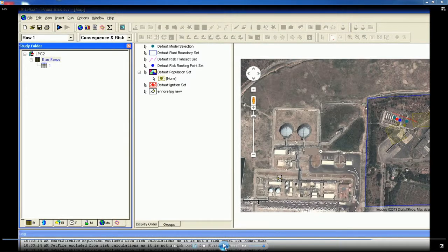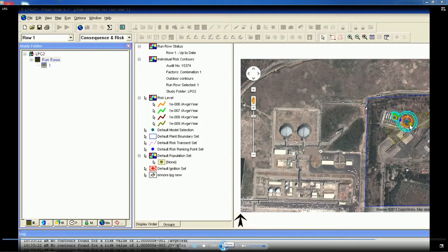Now you view risk contours, select this particular button for viewing risk contour, then select that button. Now you are viewing the risk contours for different failure modes as you see here. This is my risk contour because that is my source, that is my population rectangle as you see here, 2 rectangles, one here and one here for different intensity. We also gave a specific population concentration.